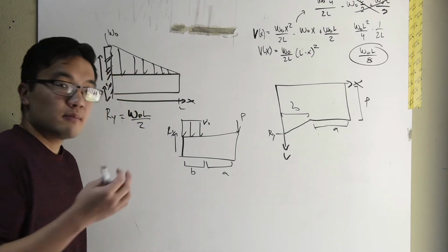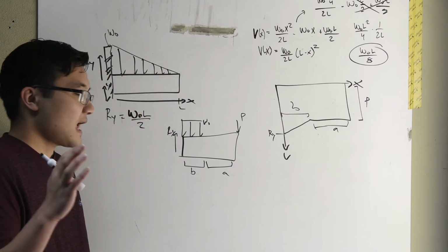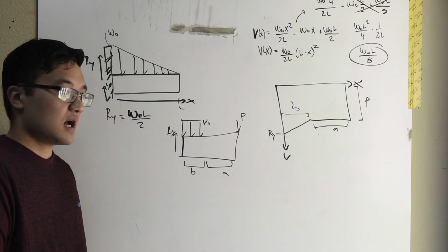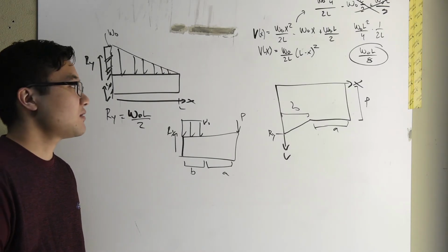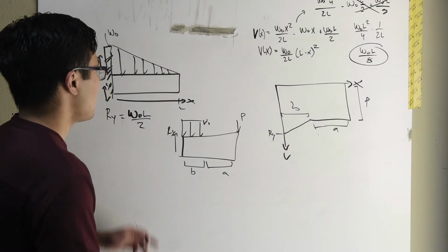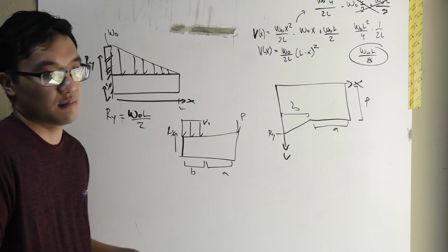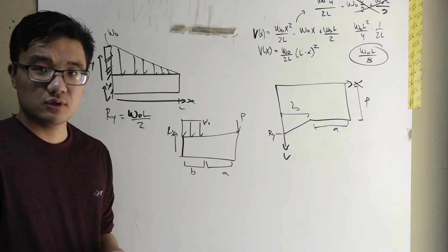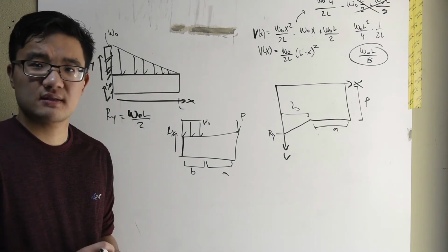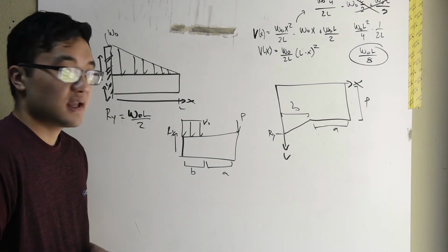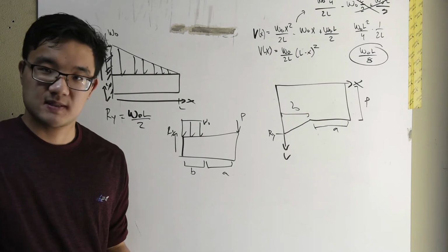Now, again, remember why we care. Cantilever beams are typically how we will represent wing loading criteria. Now, the wing might not be loaded in a triangular shape. It might be loaded elliptical. It might be loaded parabolic. We don't know. Rectangular, sometimes we take that approximation. But again, you'll know that from your fluids team.